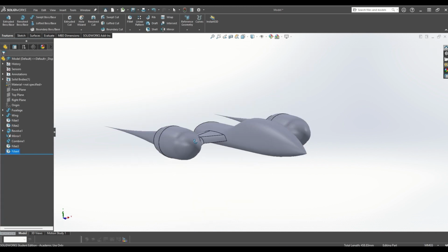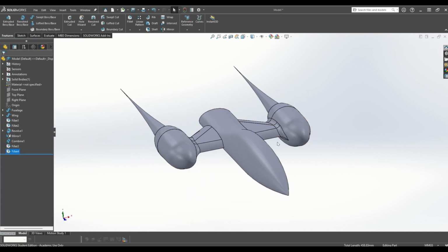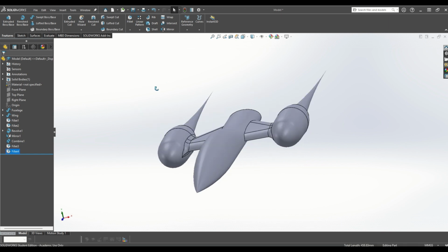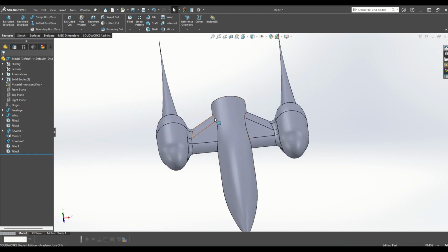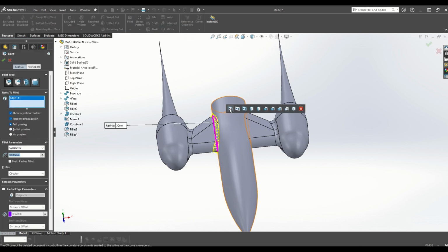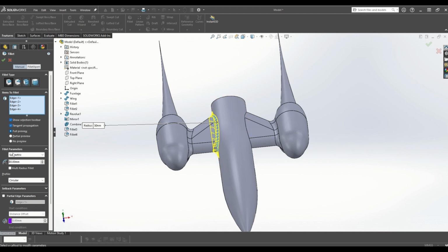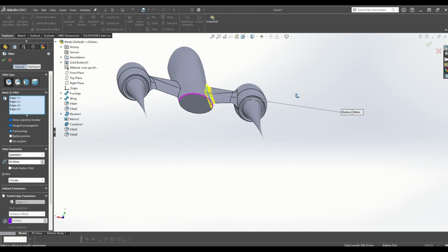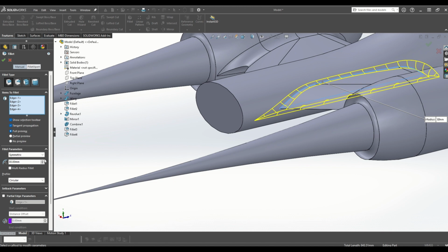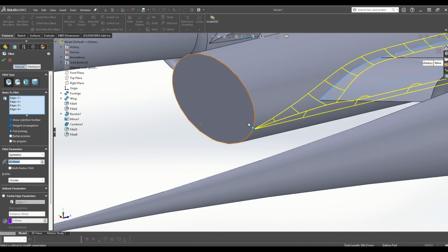All right, and now we can see that there's a nice smooth transition, which is also something that fillets are really good for. A smooth transition from one body to the next body, especially on some, let's say, aesthetically pleasing artifacts. Fillets can be quite useful for that. Now I want to create a fillet along this edge here. So I'm going to say fillet, click on this, and again the loop, and I'm going to increase the fillet here until it just hits a point to around here.